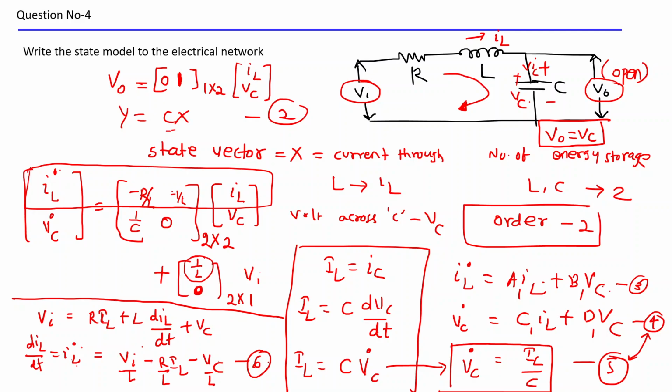After the ABC matrix is there, you have to find the transfer function. For that, a formula is there. Then from the transfer function you have to find the system total response, which we're going to solve. So these are some basics. I am just telling you how you build up the ABC matrices. So don't rely on shortcuts, sir. Shortcuts will not help always.